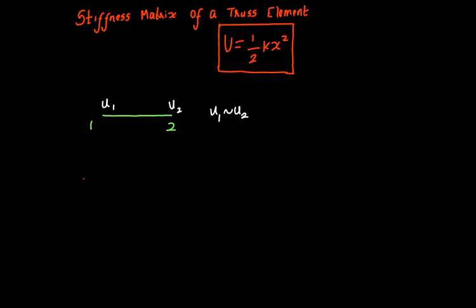So let me now define the strain energy. Strain energy U is given by 1/2. The stiffness of a bar is given by the expression AE over L. This is the formula for stiffness of the bar. That's very simple, because stiffness is load by deflection, and you can write the load in terms of stress and the deflection in terms of strain. You get back this formula AE by L. So it's not a big deal. It's very simple. You can check it at the privacy of your room.